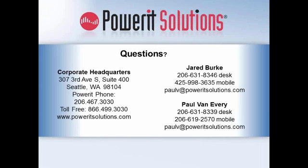Well, I found that with those rules, like I spoke about during the talk, we were able to look at our sales forecast and project and move our set point line up and down. It was very typical that we were within 1, 2, or 3 kW of our set point. So we could adjust as manufacturing requirements went up. We could increase our power level and still maintain a control point and still meet all of our production needs.